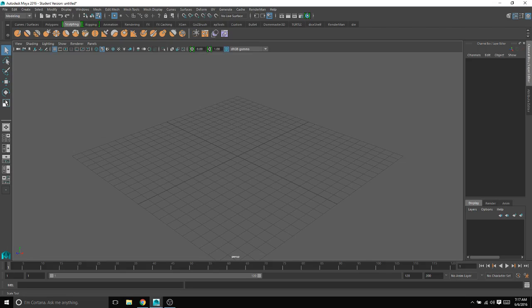You'll notice that if you put your left hand starting off with the Q, and each finger goes over one button from that, so you start off with your pinky on the Q, your ring finger on the W, and so forth, you will be switching through those tools with Q, W, E, and R. Q is select, W is move, E is rotate, and R is scale. That's done so that you can work faster without needing to move your hand as much.